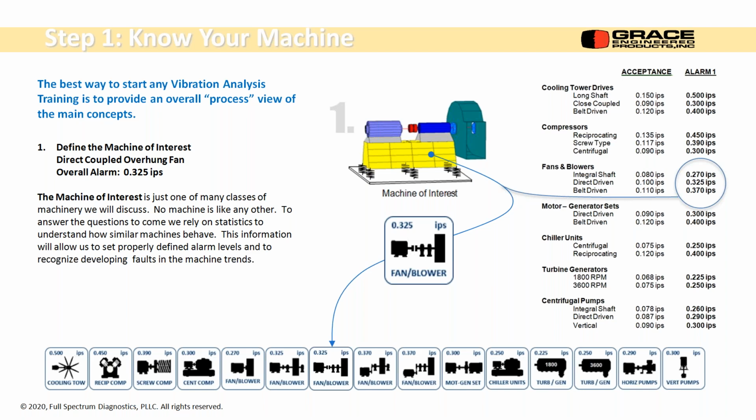Statistically, that's 3 standard deviations above and below the mean curve for the data it calculates. As it goes in, the database calculates a new mean level based on old data and the current data, and new statistical data, and your alarm curves get better and better.